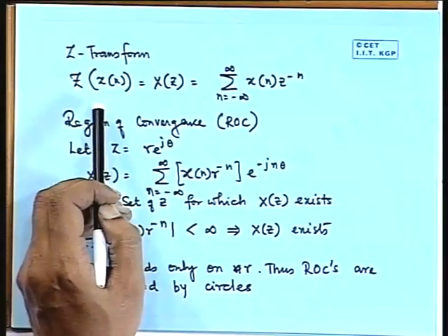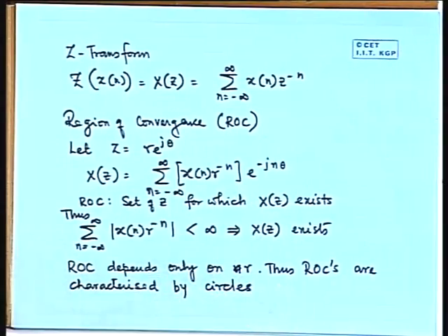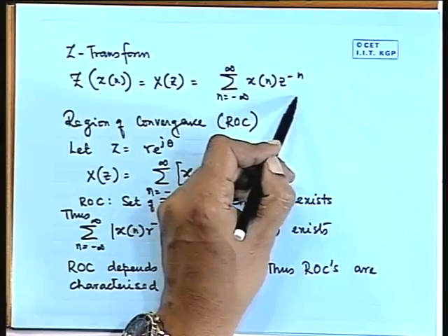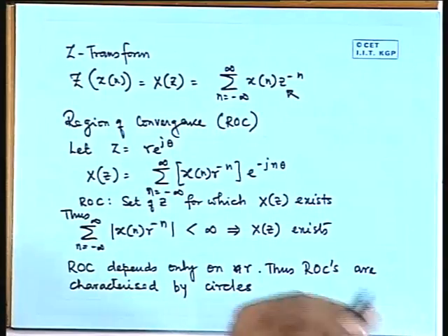So to generalize that question, let us talk about the Z transform. This is a more generalized transform in the sense that z is any complex number. What is a transform? It is like a reflected domain, just like you are seeing something through a mirror. Rather than studying the function x(t), which may be difficult to study, you transform x(t) to another domain called z, and study the behavior of x(t) through the behavior of X(z), because it is mathematically more convenient. Typically, various kinds of time domain properties become algebraic properties.